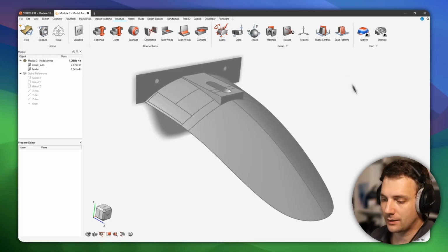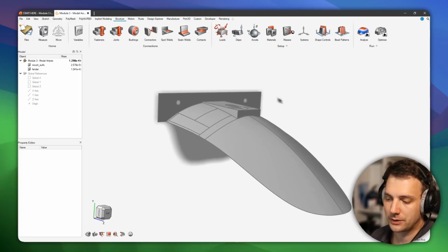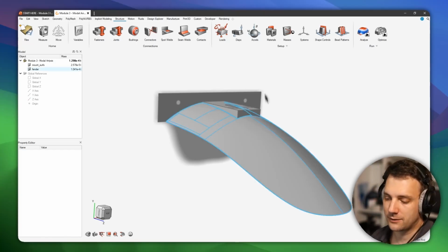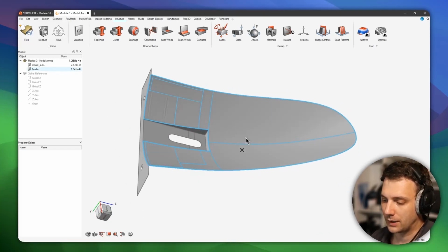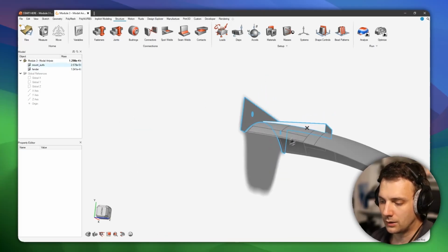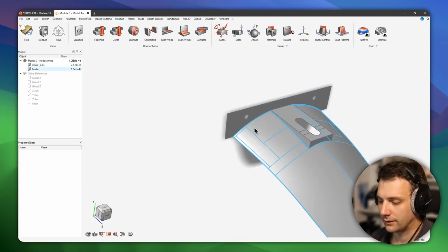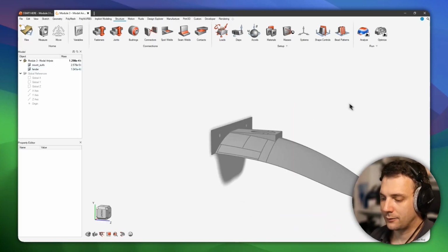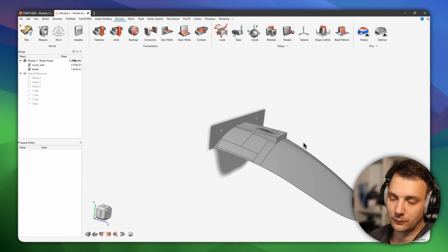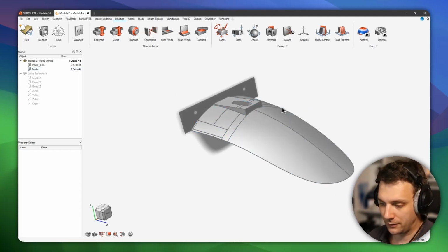But here we have the task to generate the boundary conditions before running the normal modes or eigenfrequency analysis, which then determines the eigenfrequencies for the constrained part. So you just imagine what this is. This is some sort of, I don't know what it really is, but just think of it that this is being mounted to a wall, or the ceiling, and this is being mounted to a wall. And then if you have it like that, which frequencies would occur with the constraints in place. So that's what you are dealing with here.